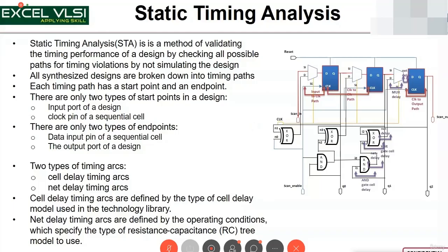Like I told you here, after the SOC is integrated, all SOC blocks are integrated, for each of the data paths you will select at least one key test case. Let us say in a particular SOC, at block level and all, you have 1,000 test cases. At the gate level, you select some 50 test cases which are critical, which cover all the paths.